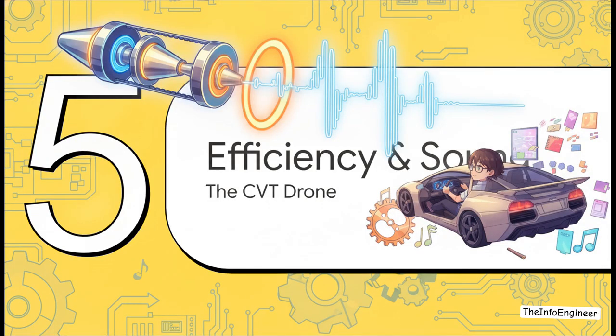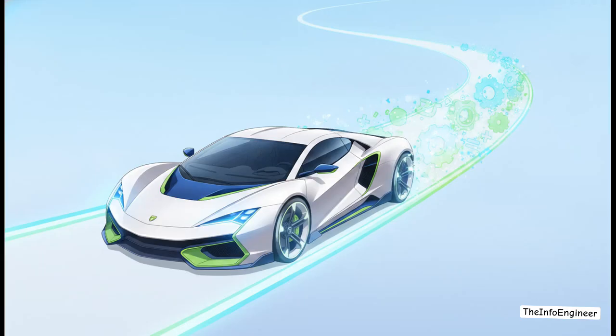Finally, Section 5, Efficiency, Sound, and Droning. Let's bring all this math and engineering back to the actual human experience of driving one of these mechanically optimized machines. When everything works as designed, the mechanical payoffs extracted from this elegant, continuous design are just massive. You get infinite gear ratios, meaning the car is literally always in the perfect gear. You get absolutely no shift shock or torque interruption. You get incredibly steady cruising speeds, the maximum possible fuel efficiency, and, funnily enough, compared to modern 10-speed automatics with all their multiple planetary gear sets, you actually have fewer overall moving parts.